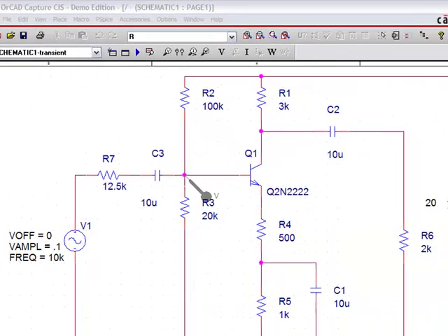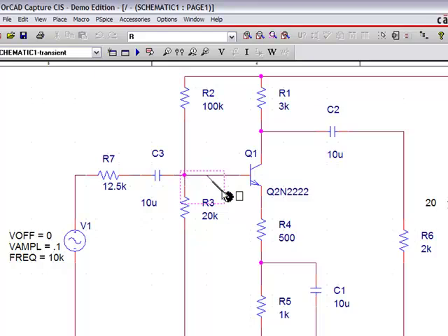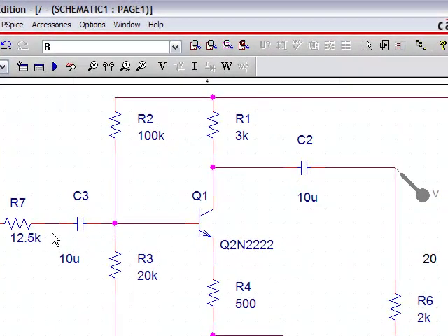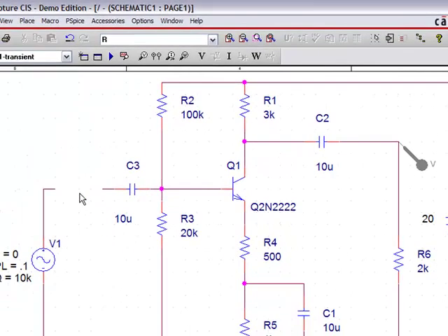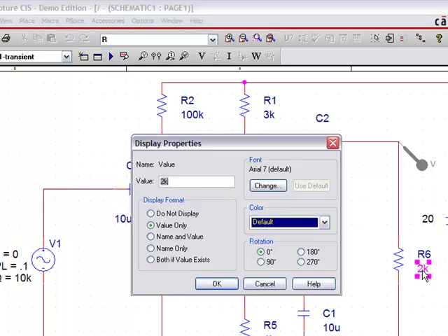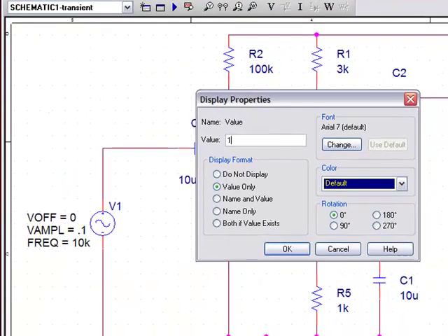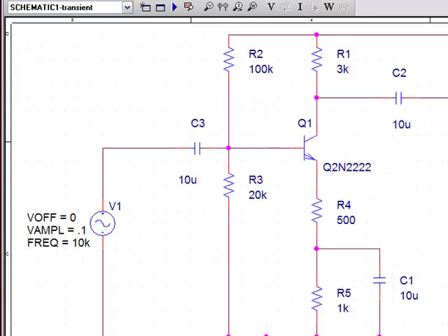The same way we can measure our output resistance. We can just move our tracer right over here. We delete our resistor and just put a wire, except we need to simulate an open circuit right over here, and since PSpice doesn't let us do it, we have to use a really big resistance, let's say 100 meg. Let's run the simulation.